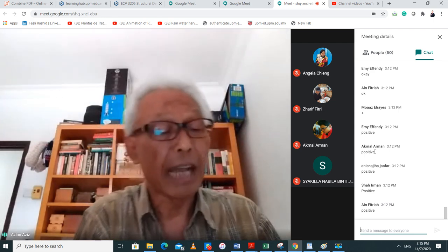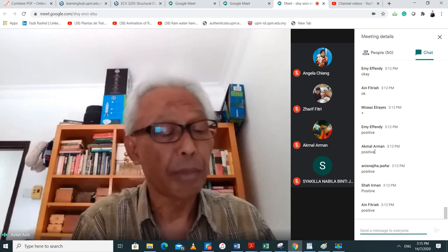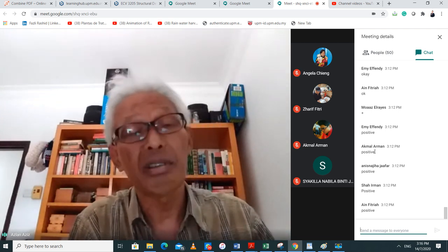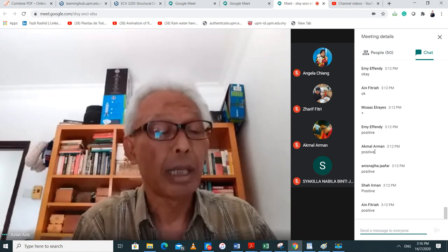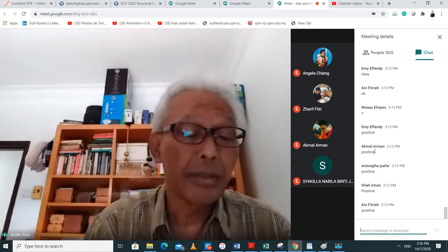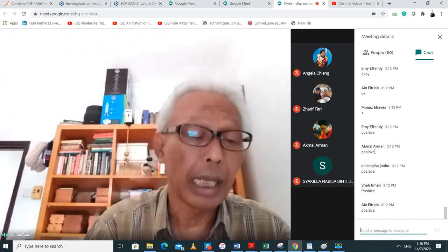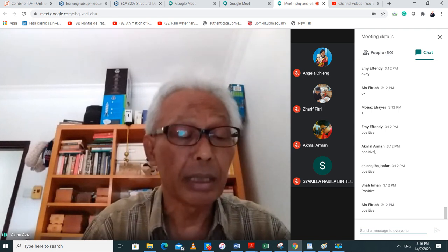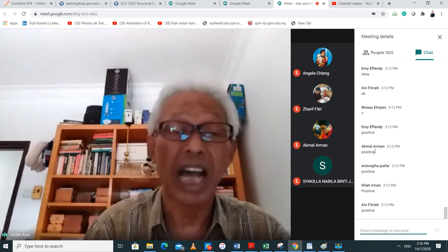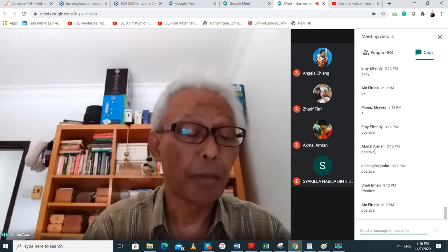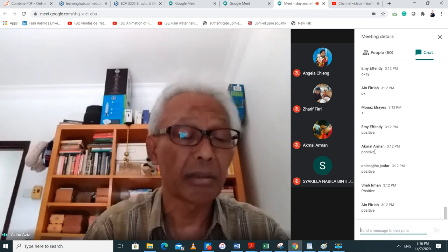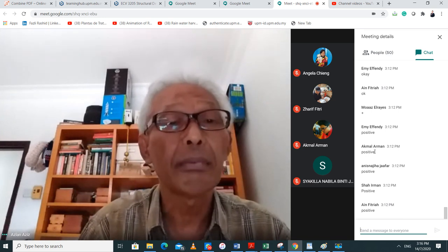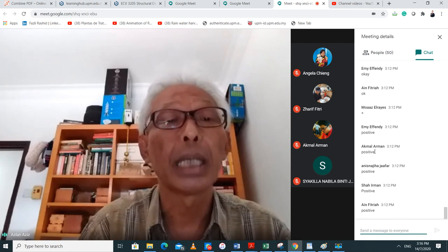So this is the depth of the base, 1.5, 3, 4.5, 6, 7.5, and so on. Then the SPT, you just take it from earlier, 4, 6, 13. Then N bar, the first one is 4, there is no average, same one. Then you have 6 at 3 meter, 4 plus 6 divided by 2 is equal to 5. Then at 4.5, 4 plus 6 is 10 plus 13 is 23. 23 divided by 3 is maybe 7.5.